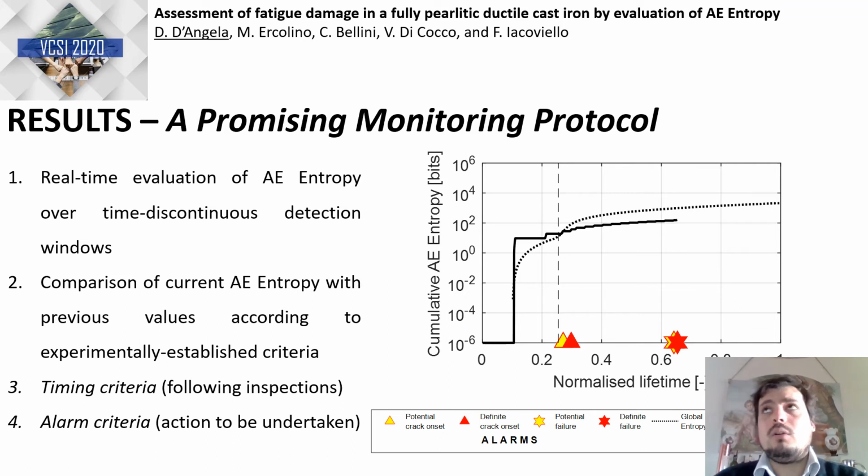Because of course we know that the typical monitoring of structures is rarely time continuous over the lifetime of the structure, but each detection window of our model is representative of a real inspection that has a very reduced time compared to the lifetime of the structure. So our preliminary protocol is based on the comparison in real time of the current acoustic emission entropy with the previous values according to experimentally established damage criteria.